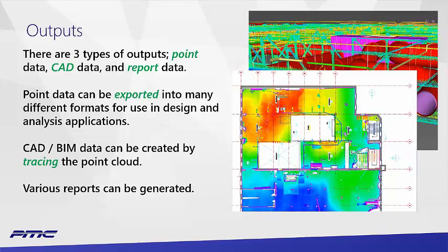A lot of different outputs can be done that fall under the report data. The exports of the point cloud should be done in manageable steps for your team. Using that data effectively is going to rely on this step being executed well, so that you're not having gigantic point clouds deployed to you. You have a manageable, workable data set. You can have CAD or BIM data created. If you're looking for something beyond CAD and more into BIM and the smart model, you need to know that ahead of time, before the people go out to scan, so that potentially additional information can be collected.